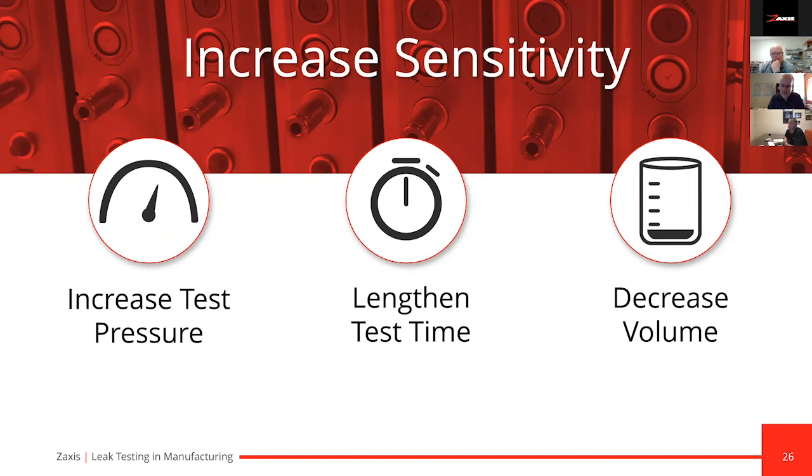We also have customers that, when parts come out of that oven, put them on a rack and let them cool down for, say, 10 minutes or 20 minutes, wherever the case may be. Just keep that same time interval going, so that whatever you validate and set your test parameters at, whether with the part at ambient temperature or at 100 degrees, you do all your manufacturing testing with the part at that same temperature.